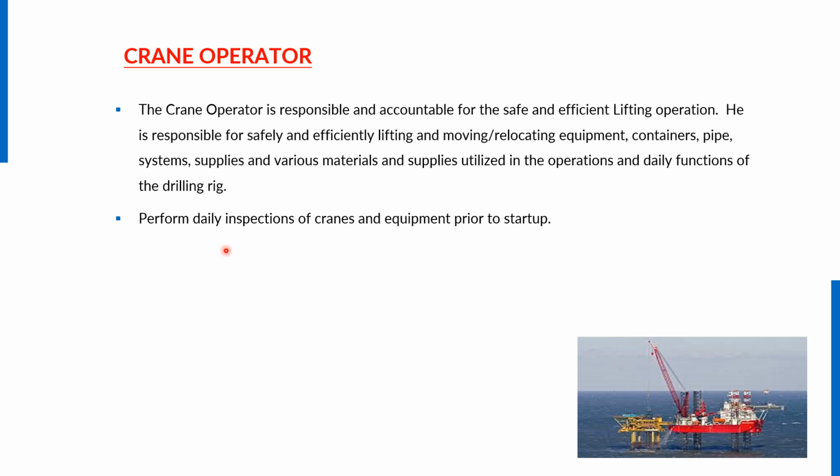The crane operator has to maintain and do the daily crane operational inspection checklist, and he has to keep it in his cabin for any time the rig HSE or client HSE come, and they can ask about that. And one thing here I want to share, that the inspection checklist which is filled every day by the crane operator before starting the crane, in the pre-tour, that inspection checklist will be maintained at the rig HSE office for 3 months for inspection purposes.